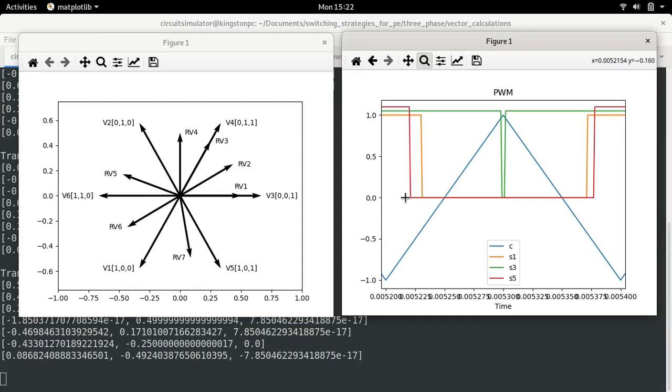This is all due to comparison between modulation signals and a triangular waveform, and this can be displaced as the system becomes more uncertain. Therefore, in a real system with harmonics and with other non-idealities, this could face some fluctuations. And when you have such fluctuations, then you can't guarantee that you are using all your voltage levels in an optimal manner, right? So therefore, this coordinated strategy is still better.